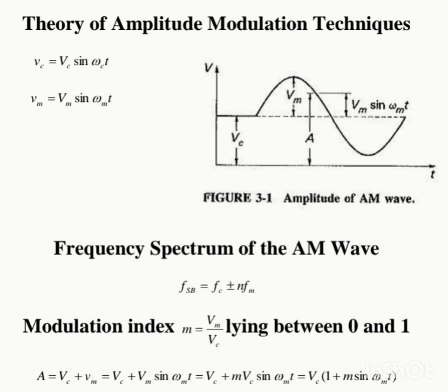In amplitude modulation, the amplitude of a carrier signal is varied by the modulating voltage, whose frequency is invariably lower than that of the carrier. In practice, the carrier may be high frequency while the modulation is audio. Formally, AM is defined as a system of modulation in which the amplitude of the carrier is made proportional to the instantaneous amplitude of the modulating voltage.